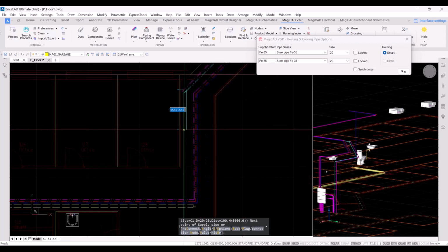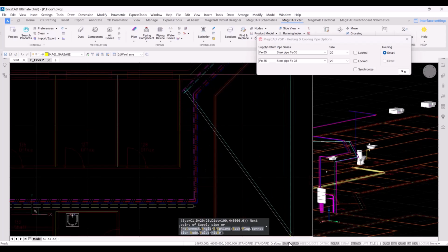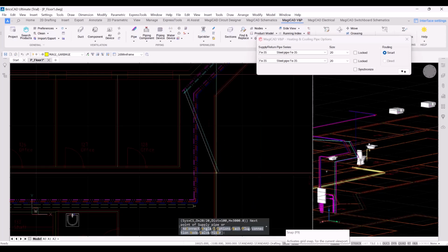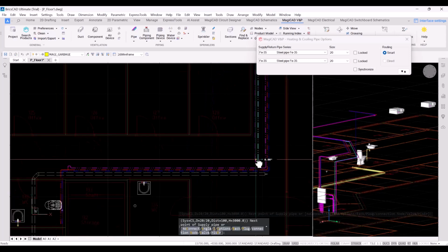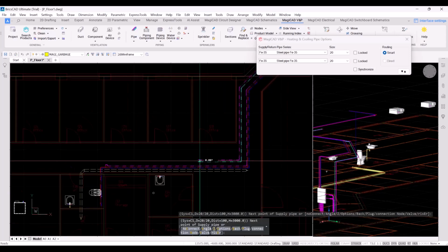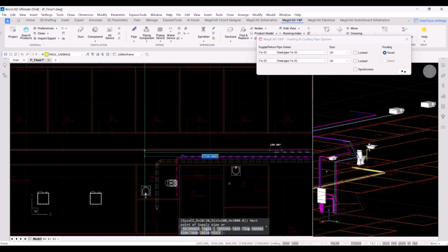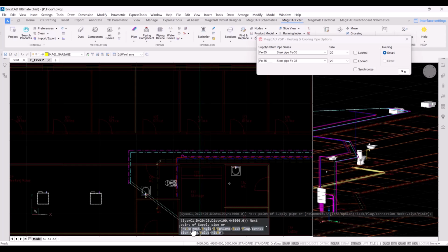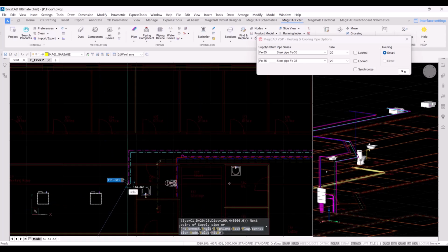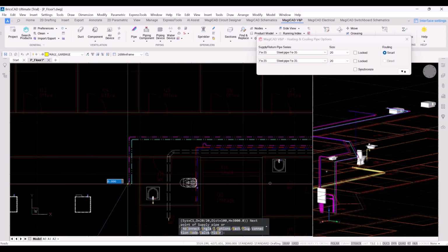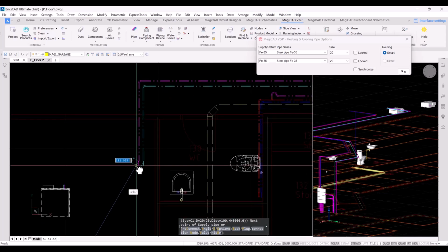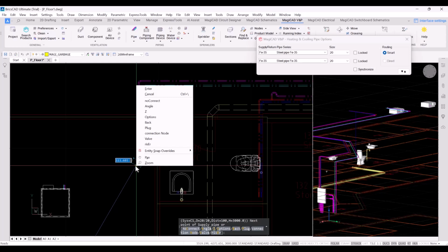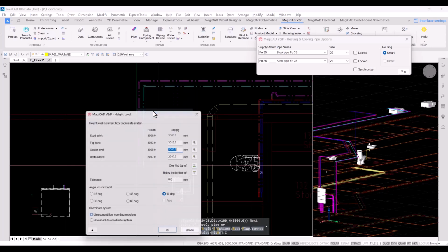So when drawing pipes and when doing product installations, it's good to make sure that the snap functionality is on. So it's easier for us to make device connections and also connect open pipe ends to each other. Here, while the drawing command is active, I have a number of different options. I could, for instance, install a component here, plug the pipes, make a riser, insert a valve, or make an elevation change. I will get the same options here with the right click.